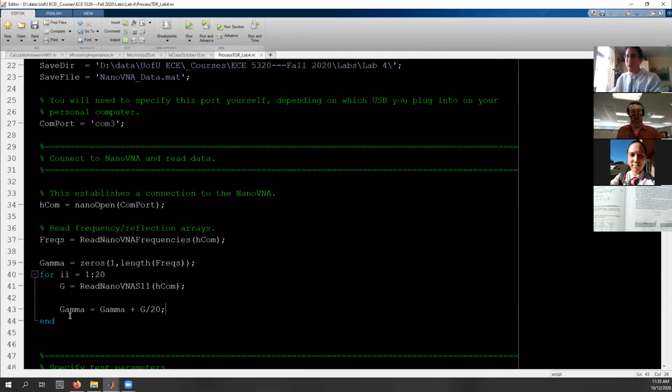So it's pretty straightforward to do averaging if you want. The one thing I'd really like to do is have it probe more of the frequencies, because right now it'll only do 101 samples between your start and your stop frequency. It would be nice if you could have it chop it up into sub blocks so you get better resolution in your output. But even so, it seems to work fairly well as is, so I'm not too much in a rush for that.